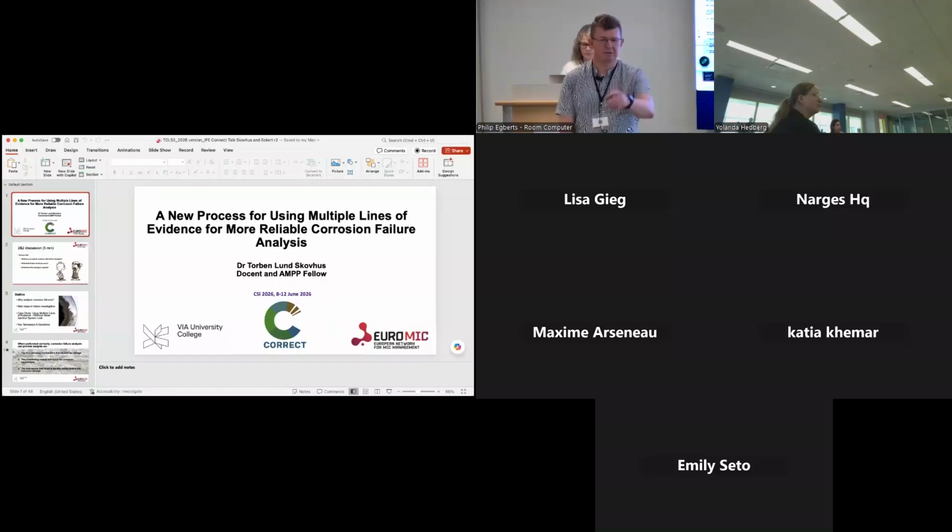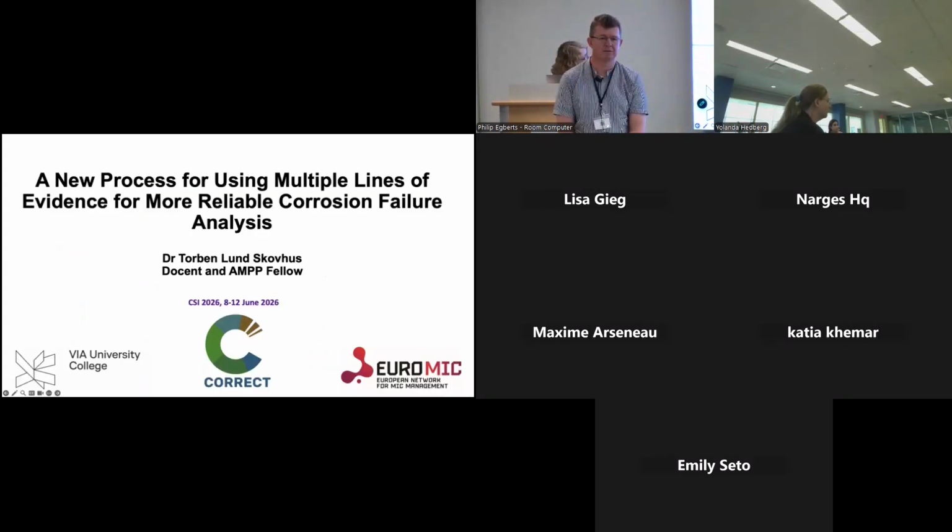Okay. And you? I did a publication with the Canadian Nuclear Laboratories. They did a test loop of molten salt. That was intended to run for a year, lasted a week. Wow. The whole step of the failure analysis was I got sections of the tubing from different parts of the loop, following the current, the way the salt moved.